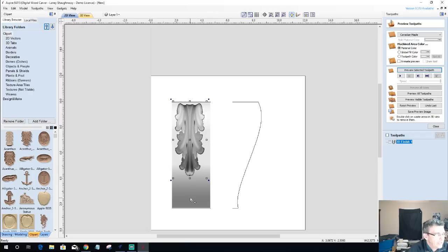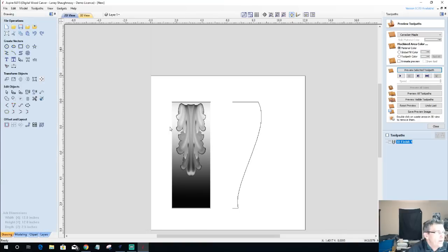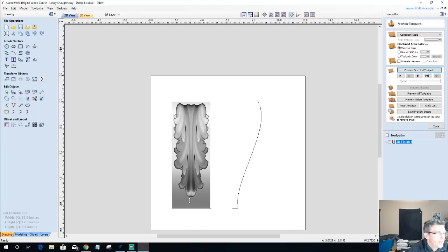With him selected, I'm going to select my main body model last. I'm going to go into my alignment tools and basically get him centered. That way I can come in and select my top component. I'm going to hold my shift key down and drag it out. I want to stretch it out right to the edges there. But I also want to pull this down to about here. And so if we look at this in our 3D view, let's go with kind of a split view here.